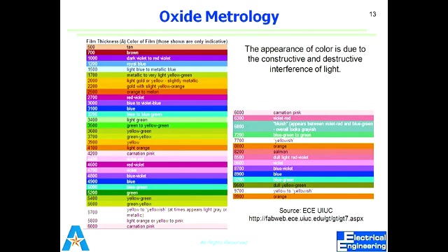As thicker and thicker oxide comes in, the color keeps changing, and for 1200 angstroms there is royal blue. For 1500 there is light blue to metallic blue. Mostly in our case, our wafers would have this much thickness, 1200 to 1500 angstroms finally. So finally the wafer should have this color, light blue or royal blue.